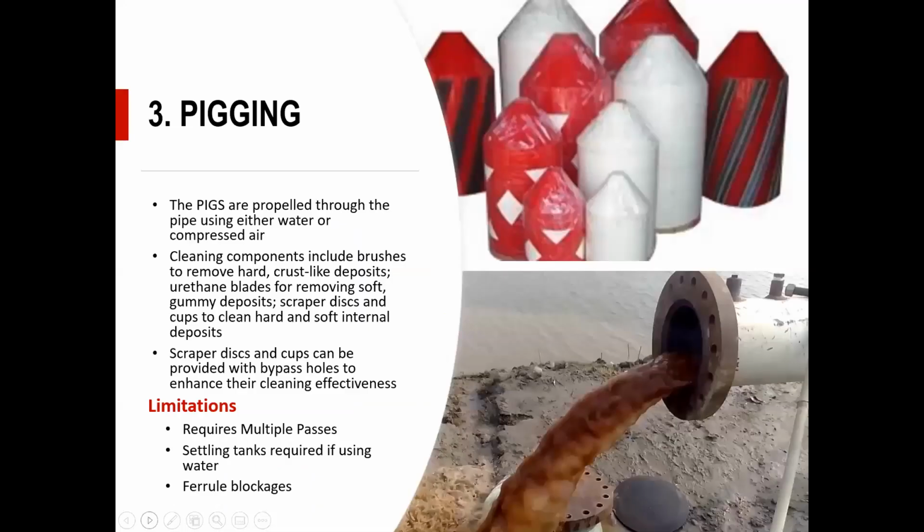When we're looking at pressure pipes and water mains, process pipe work, then one of the popular methods still being used is what we call pigging. So on the right hand side we have the pigs. They're foam, they can be metal, polyurethane. They can be soft, they can be aggressive, and generally the selection of the pig is designed to suit the pipe that you are cleaning.